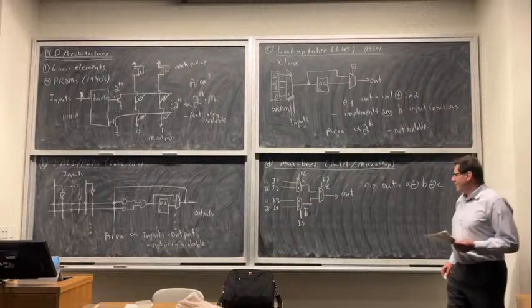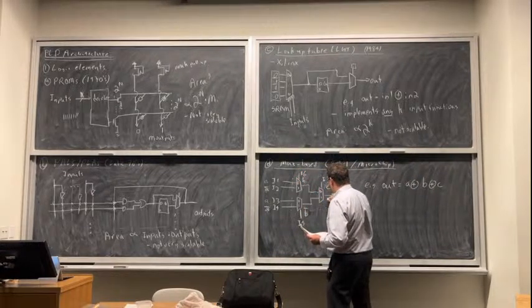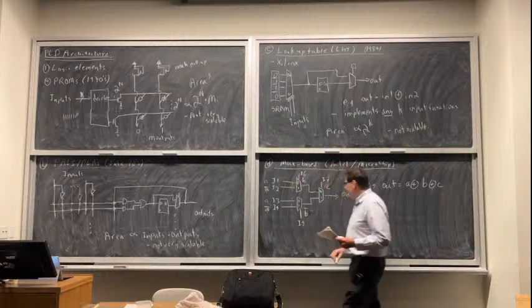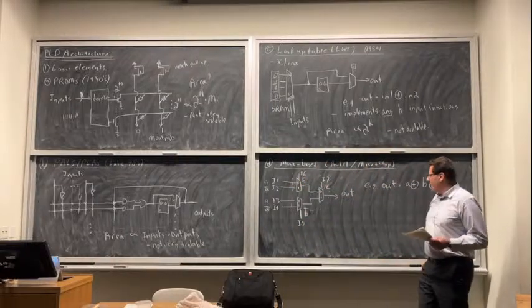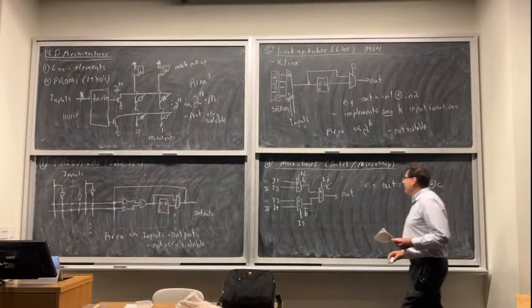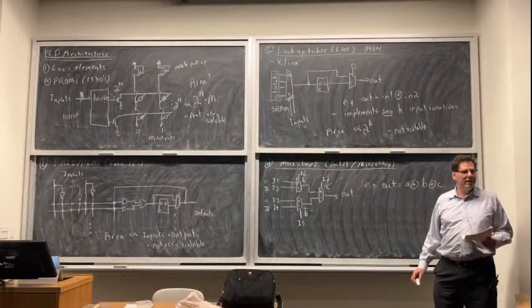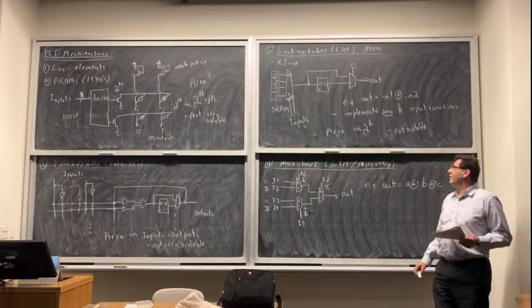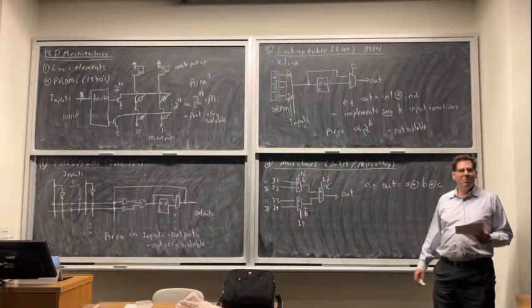Can I do a 3-input XOR in that 2-input lookup table? So this is a 4-to-1 mux, by the way. That's actually how you build a 4-to-1 mux, a cascade of 2-to-1s. So I've got part of that lookup table, but instead of SRAM cells, I've got just signals connected to the input here. Can that 2-input lookup table do a 3-input XOR? Is there any way to do that? What do you think?